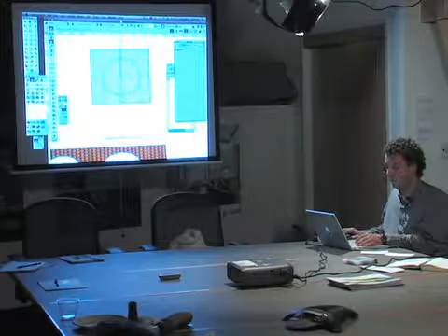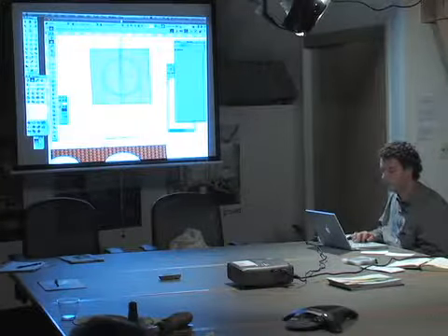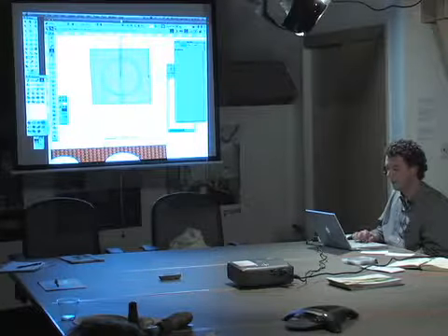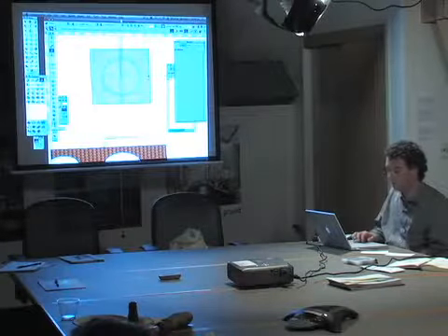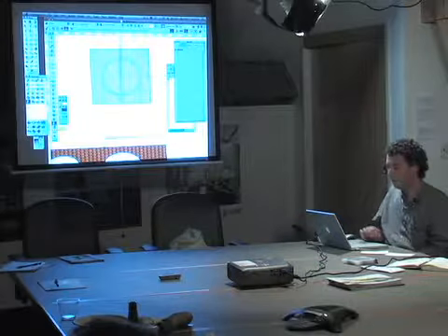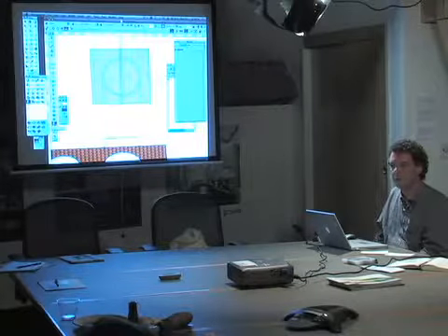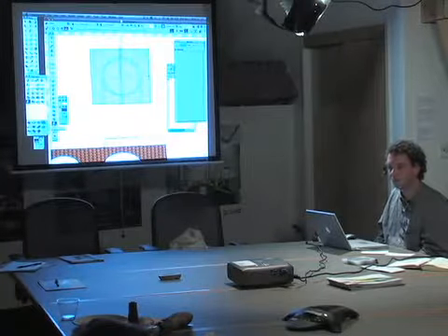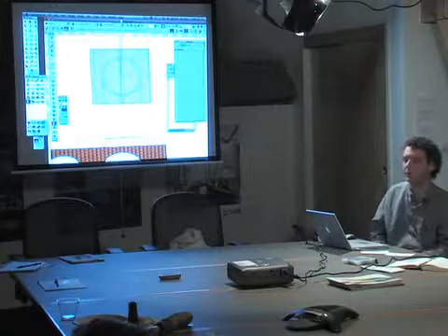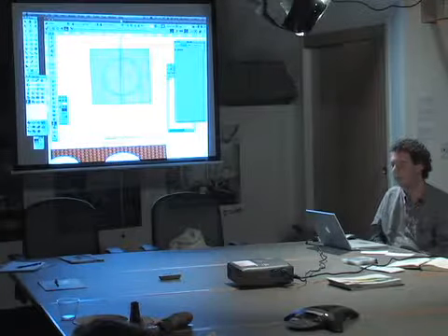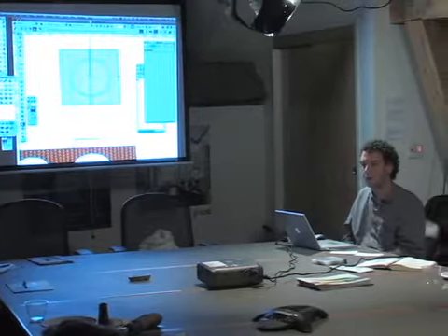We do have some of these other 3D modeling features that are still in here. This was a push-pull, and down here is the extract face. That also has been in the program for quite some time, but it's much more robust. You were able to extract a face, but it would create a NURBS surface that you could apply a texture to independently, but you couldn't apply these 2D graphic attributes to it. So I think the big improvement in 2011 is the graphic attributes working in 3D now.